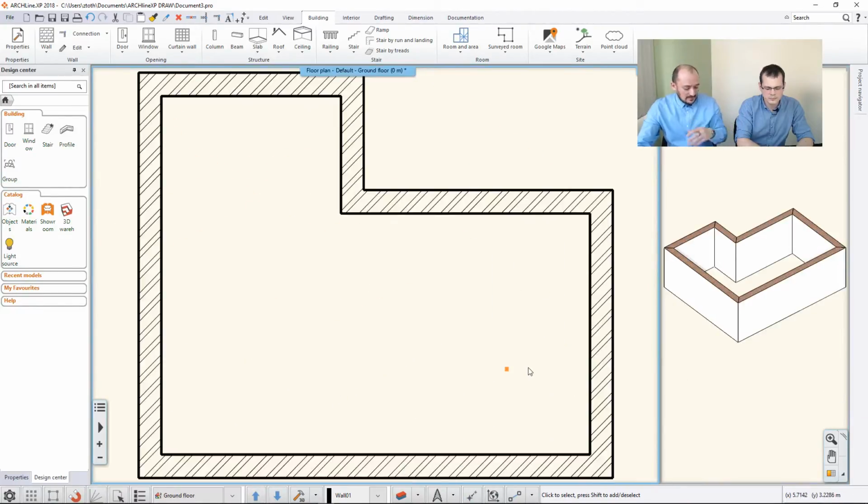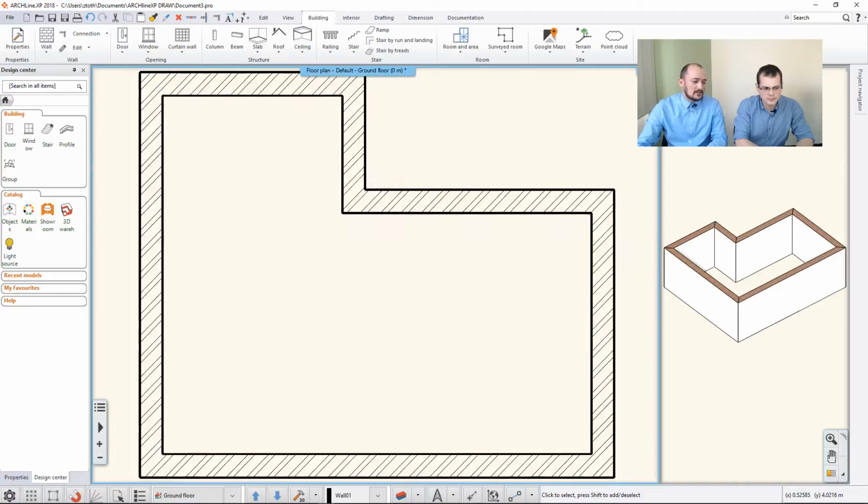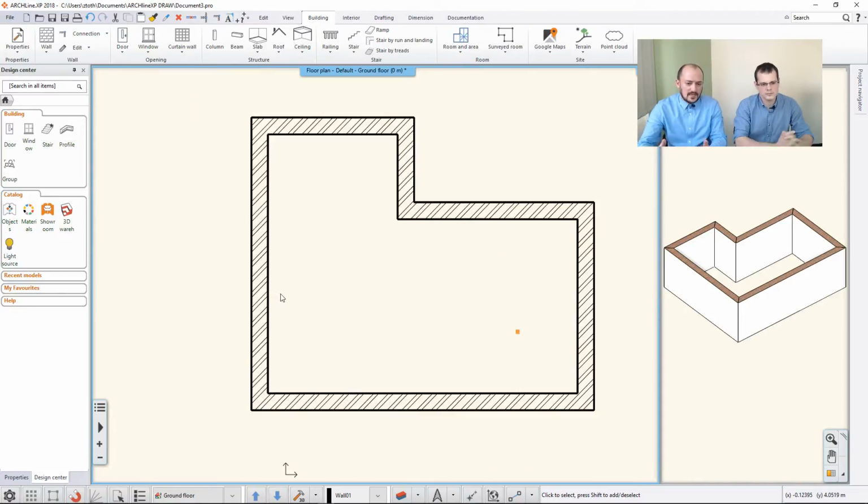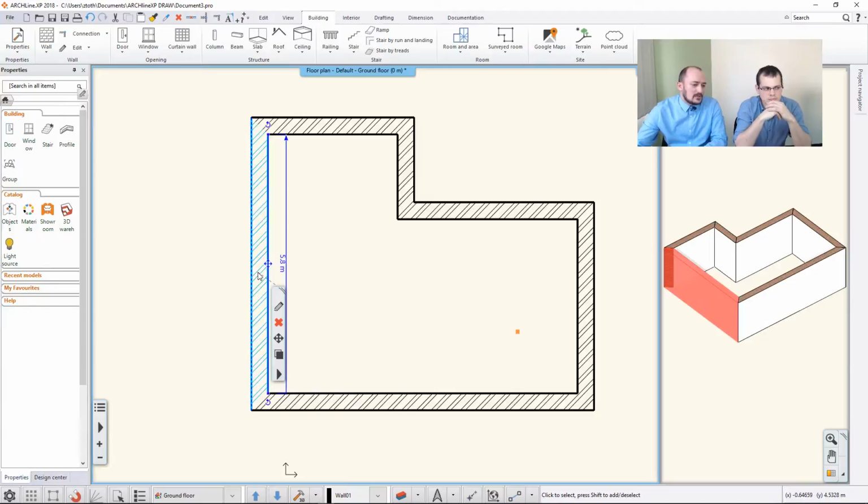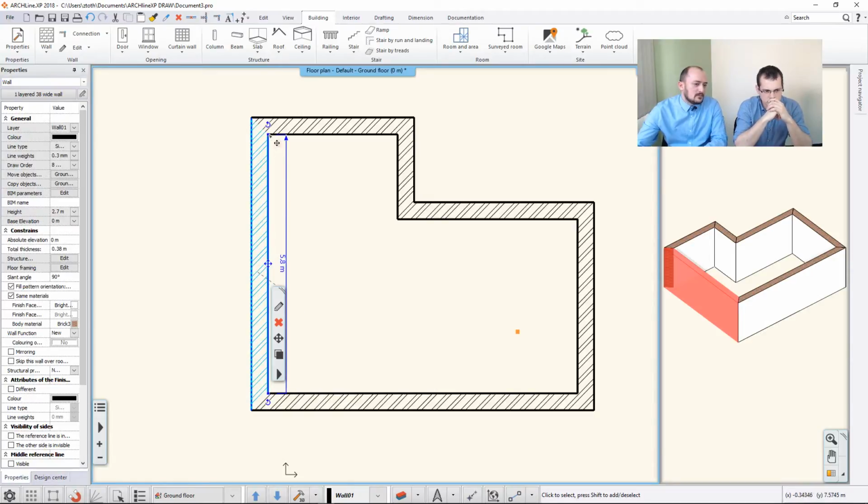To go on, I actually have this sort of extension, a very small surrounded area. It's about here. It's for a desk or some commode or some sort of small furniture. Do you modify the existing wall, or do you have to redraw this? You have several options. First, you can always select the existing item and move its corner points. You can even insert breakpoints, like an endpoint here, an endpoint over there, and change the whole thing.